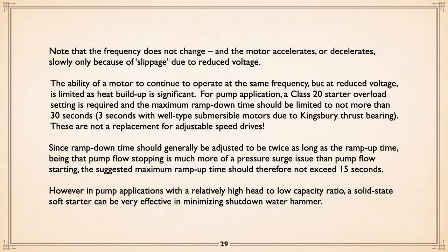Submersible motors have thrust bearings built into them. As I said, they're not a replacement for adjustable speed drives. Since ramp down time should be adjusted to be twice as long as ramp up, ramp down is where water hammer occurs. Suggested maximum ramp up time should therefore be half that, 15 seconds. In pump applications with a relatively high head to low capacity ratio, they can be very effective in minimizing shutdown water hammer. I've seen it where even a few seconds of ramp down on some systems will make all the difference in the world, and water hammer virtually disappear.